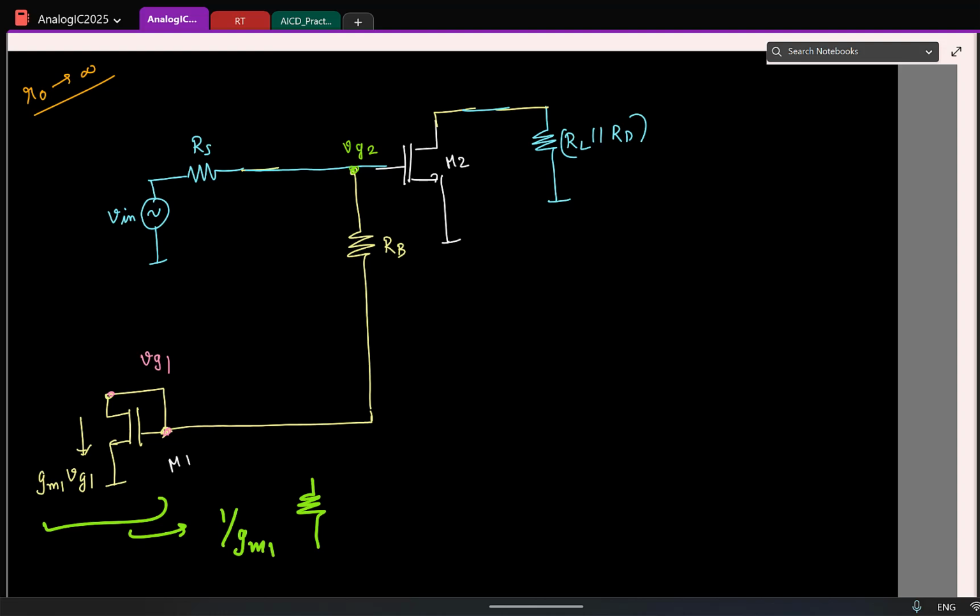Exactly. Remember that a MOSFET, how many terminals does it have? 3 terminals. But here I am basically shorting gate and drain. So how many terminals do I have? So how many port network is this? 1-port network. We already saw any nonlinear 1-port network for small signals is a resistor. Should not be surprising at all that this happens. And similarly in the future, anytime you have a 3-terminal element where some terminals are getting shorted, so that effectively we end up with a 1-port network, you can replace it for small signals by an equivalent resistance.